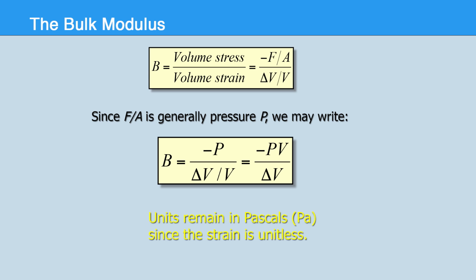Bulk modulus is defined as the ratio of the applied pressure, known as the stress, to the resulting relative change in volume, known as the volumetric strain of the material. It is denoted mathematically as pressure divided by volumetric strain, where pressure is the increase in the pressure applied to the material. Volumetric strain is the relative change in volume of the material under the pressure. The negative sign indicates that increasing the pressure typically causes a decrease in volume.